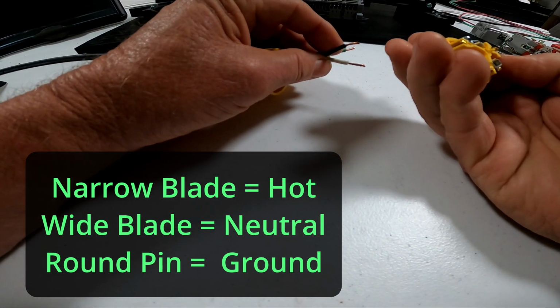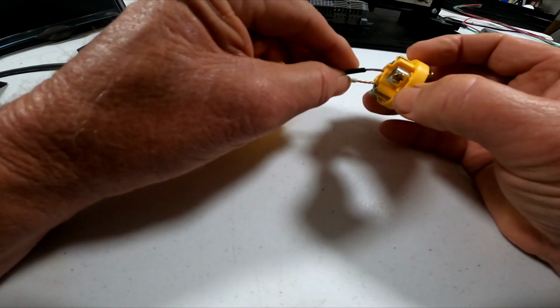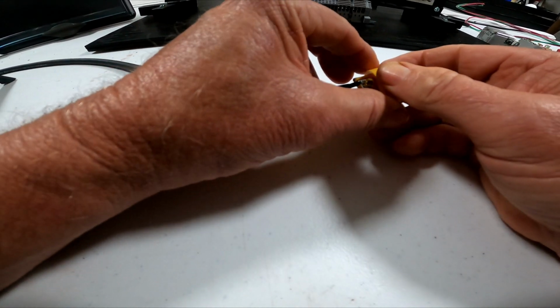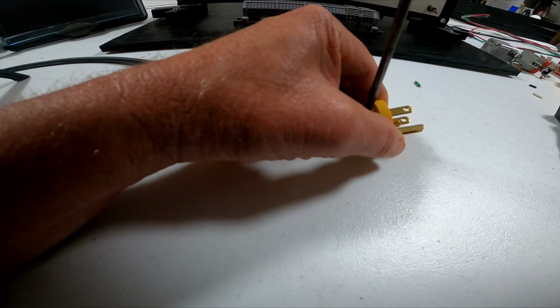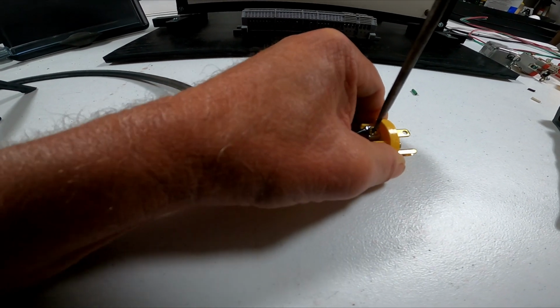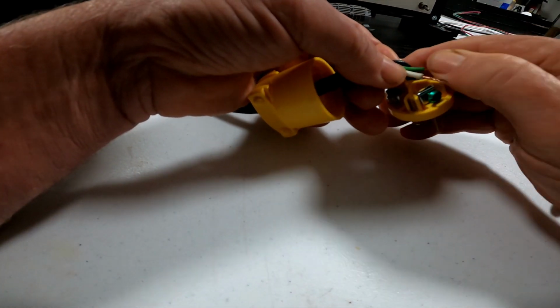Okay, black is always going to be the hot, and hot goes to the gold screw. So we see a gold screw there, so we know that the black wire goes to the gold. Then we tighten it down. Now we inspect it to make sure there are no tiny wires sticking out anywhere. And I don't think there are.